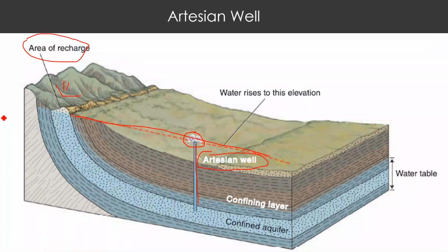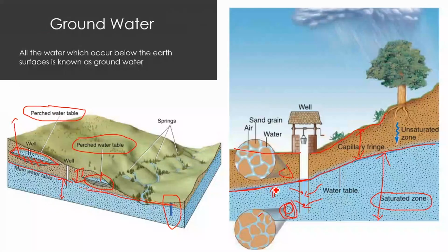So the water up to this level is not moving further up, because it is in an equilibrium condition. Okay, so this level we call the water table, and I don't know whether you observe this, the water table follows the topography.